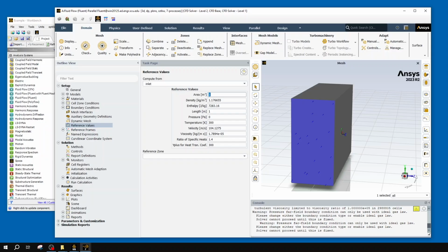So for the wing I imported, it is 0.839055. So that is important to put in as we have Fluent calculate our coefficient of lift and coefficient of drag for us. Just double checking my reference again to make sure I don't miss anything.